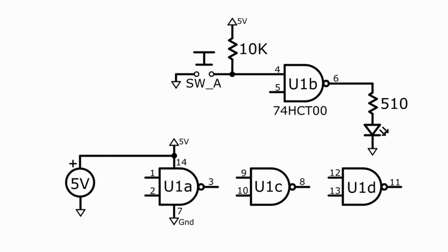It comes into play when the push-button switch is released. The contacts will no longer be connected. We can therefore entirely ignore the left-hand part of the switch, which is no longer connected to this NAND gate. It would be easy to conclude that the voltage at pin 4 is now high, since it's connected to the 5-volt power supply through the 10K resistor. While that's true, the reason is a little more subtle.